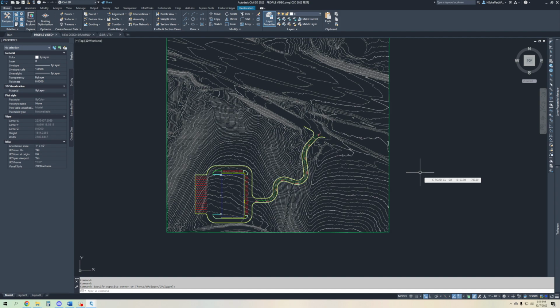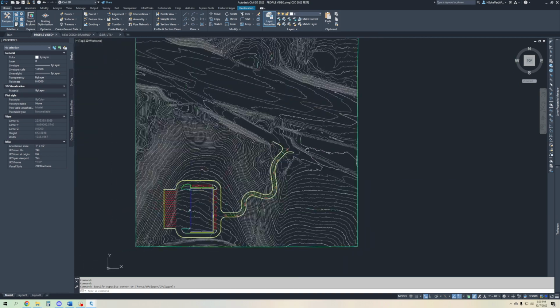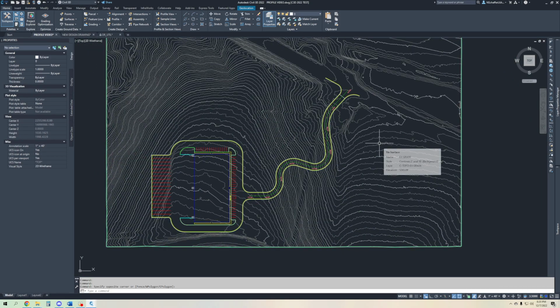Now we've talked about surfaces, so you know that a surface is elevation data for whatever area you're working on, and we have our cross section like we had created previously in part 1. We have our alignment here. So now in this part, what we're going to do is actually create that cross section, and that cross section is called a profile.